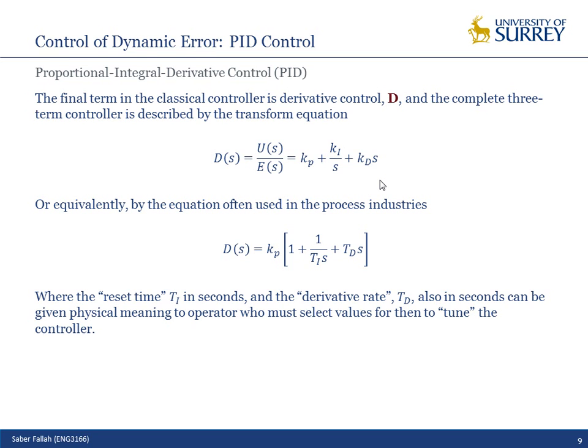But in theory it's good, but in practice we can't use the derivative controller. Or if we want to use it, its gain should be small. What's the reason? Because it introduces the S. Okay, S is the derivative. So what's the drawback of using derivative control in practice? It reduces the type number of the system, so it reduces the...